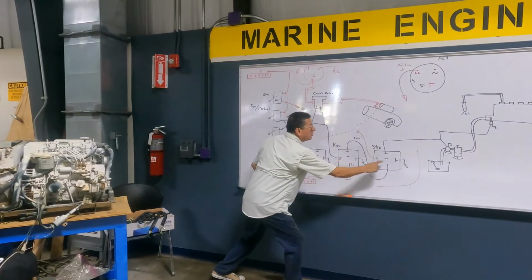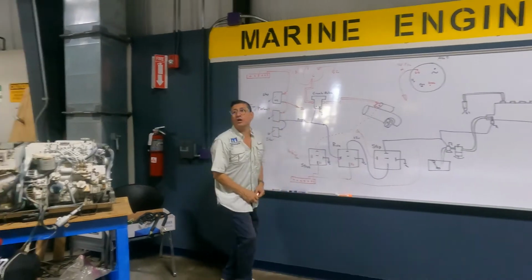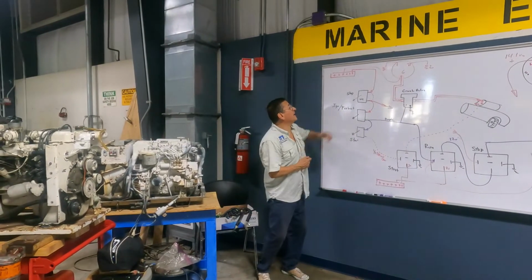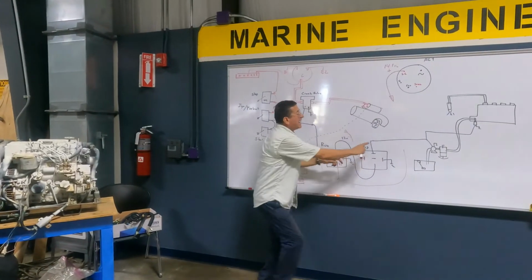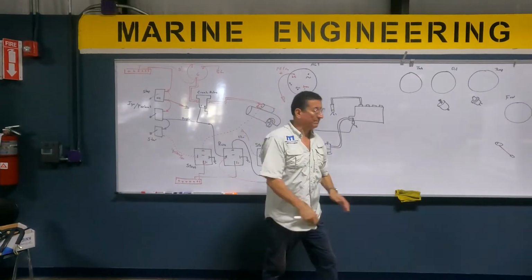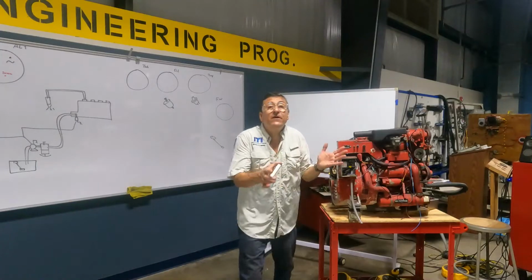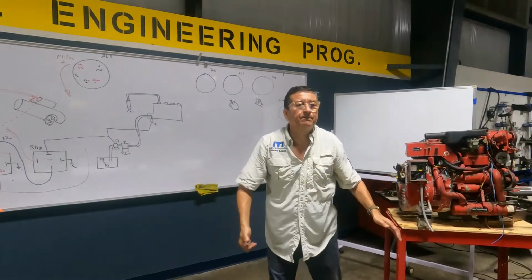That cable continues all the time here because I have constant power here. Yes or not? What happens when I press this button? It interrupts this current and this one, so no fuel, no solenoid, and the engine stops. Finito. This is universal, for outboard, inboard, and generator.